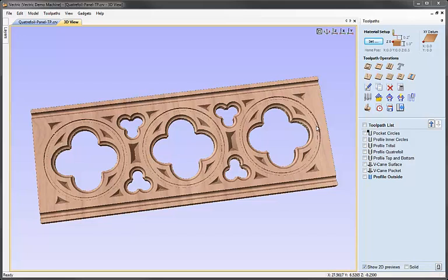One key thing that we looked at there was how we needed to use different toolpaths for the different depths of cut that we wanted to use, even though ultimately we might end up saving those as a single file to send to the CNC. So the first set we calculated were on the surface at 0 for the trifoils. The second set we calculated need to go 1/8 of an inch deeper to allow for the fact that we'd pocketed out this inner surface here.